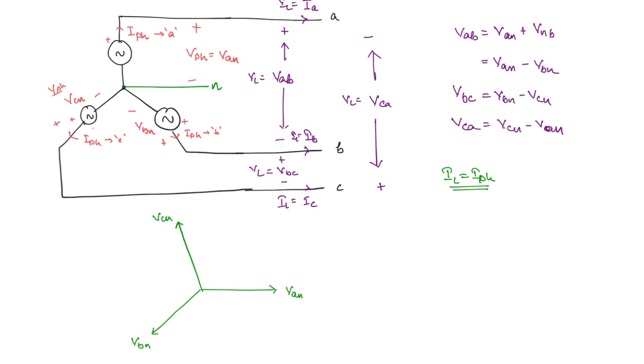Now we want to express the line voltages. Okay, so VAB is VAN minus VBN, right? So this is VAN you have, VBN is here. Now minus VBN will be opposite, 180 degrees opposite. So that means this is going to be minus VBN. Okay, now if you add these both phasors, then you are going to get VAB. So this you can do by the parallelogram law of addition. So this is going to be VAB.